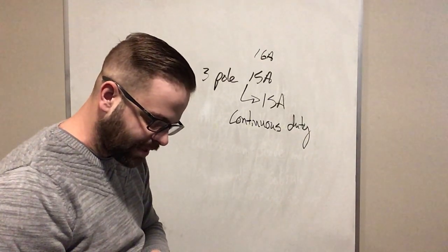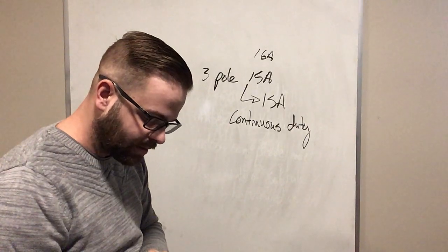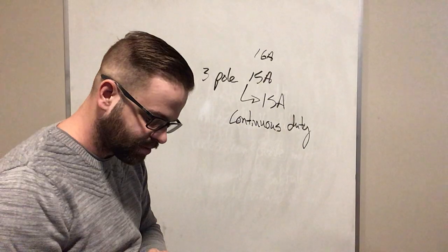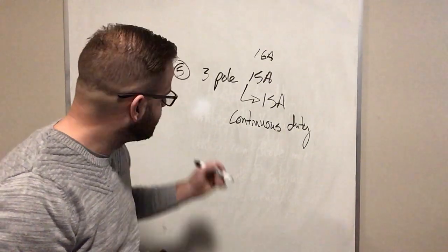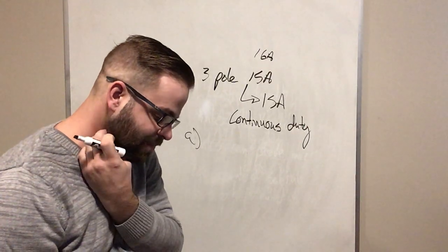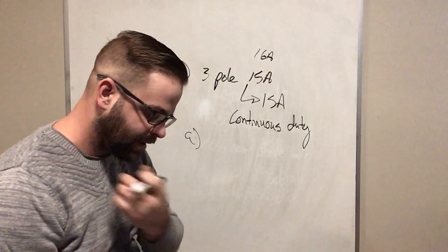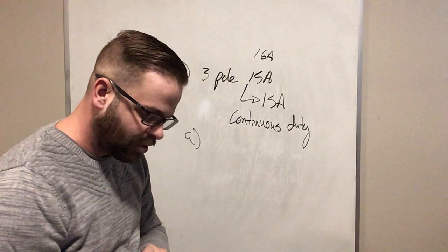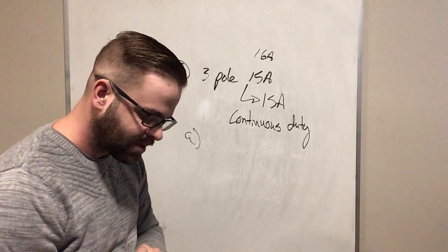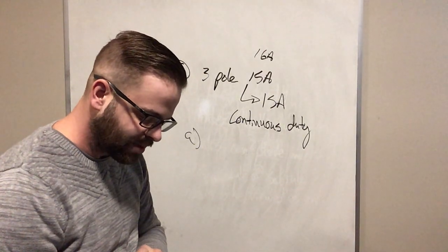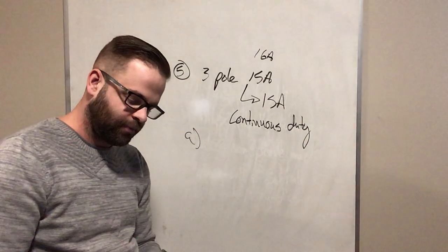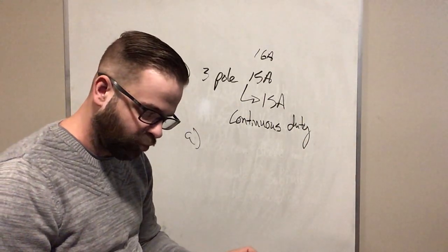So the continuous load as determined from the calculated load shall not exceed the continuous operation marking on the fuse, switch or circuit breaker. And so this is A, except as required by item B, which we will get into in a sec, shall not exceed 100% of the allowable ampacity of conductors selected in accordance with section 4.